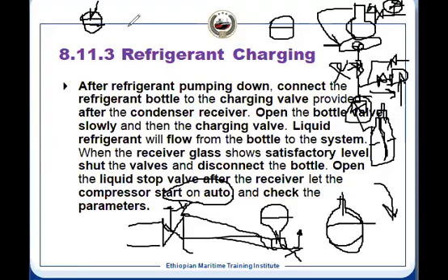So, Abraham, is it clear? In both cases you will have to do the pumping down, and once you have pumped down, after that you do the charge. So this is a must, and you will know exactly what correct level will be maintained, as well as how much you have added. That you also record. There can be a separate logbook, or you write it in the engine logbook, the chief engineer's logbook. So this is the way charging is done.